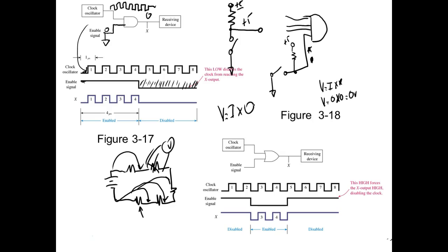0 volts. So by George, guys, you're going to get yourself killed. You go over there and measure across a closed switch and you measure 0 and you say, well, there's no voltage here. You reach up there and you're going to replace that switch, and what do you get? Your butt zapped, because a switch drops no voltage. Y'all understand that? That's the biggest mistake. I'll put that on the test.